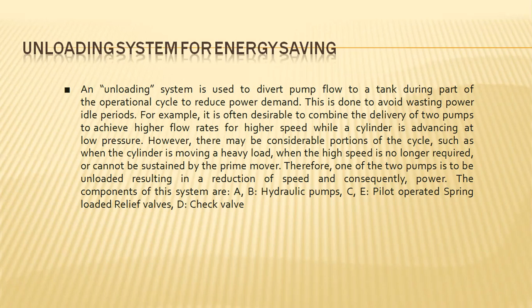Till now we have been utilizing the pressure relief valve. Simultaneously, here we will be utilizing these unloading conditions, nothing but reducing the power as per the demand required. Generation of the highest pressure leads to damage of the system, and hence this unloading of pressure plays a major role. This is done to avoid wasting power during idle periods.